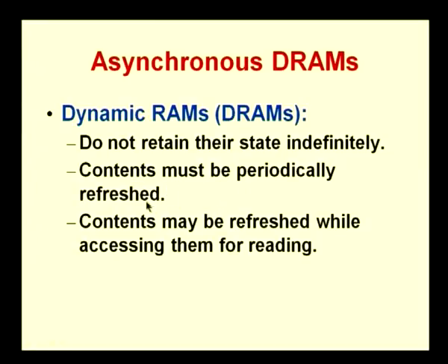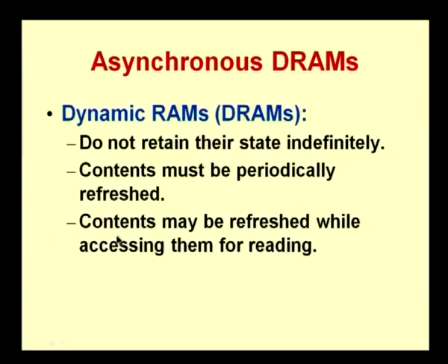What do you mean by refreshing? Because the data is likely to be lost, I will have to write it back and make sure that the data is maintained at the same value. Normally the contents may be refreshed in dynamic RAMs by accessing them for reading. If you just access it once, you will find that it is refreshed again.